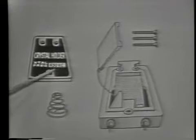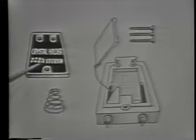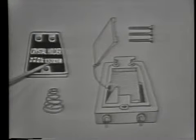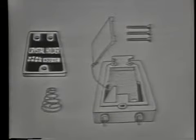The crystal holder cover usually indicates the fundamental frequency for which this particular crystal was cut. In this case, the crystal was cut to oscillate at a fundamental frequency of 430 kilocycles. Now, so far we've seen the physical characteristics of the crystals. Let's now see how the crystal reacts electrically.